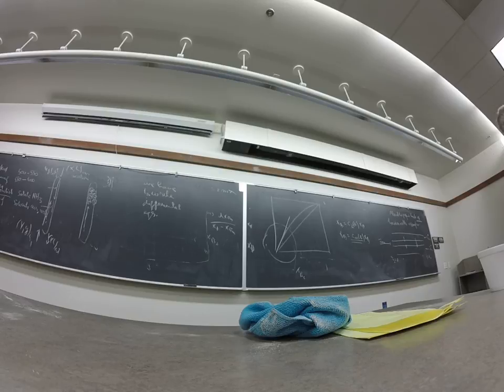I do not want you guys, if you take first lab in the fall, to come use the log formula for other heat exchangers with different geometries without a lot of comment. This is the only exchanger for which, even with these assumptions, I can get a form with a log in it. That's the first thing.